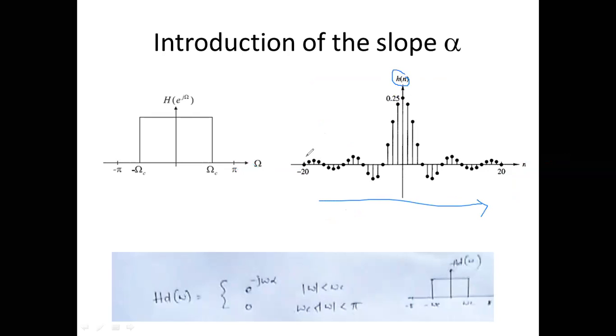Here it is nothing but count the number of non-zero values in the impulse response, in continuous. The zeros in between shall be counted. So you can see in this particular system, there are totally 41 values. So the order of this filter is 41.